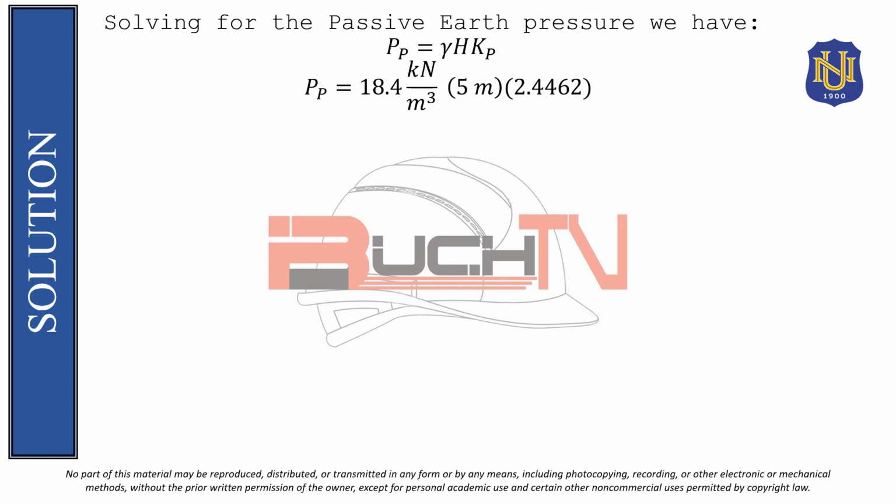So, that is P sub P is equal to 18.4 kilonewton per cubic meter times 5 meters times 2.4462. Calculating that one, that will result into a value of P sub P is equal to 225.0504 kilopascal. The unit is kilopascal because this will cancel out. This will be 2. Then, this will be cancelled.